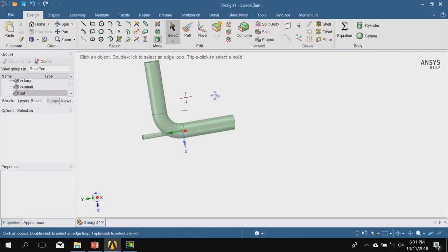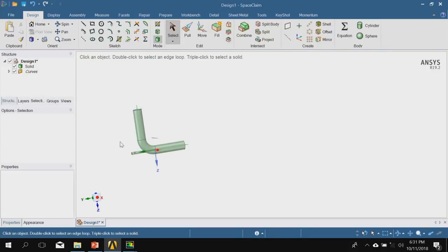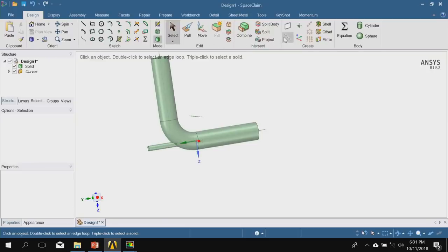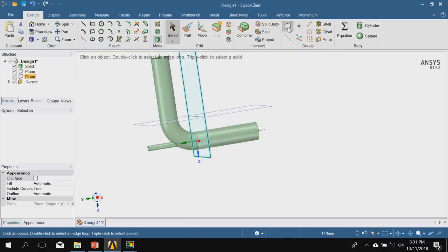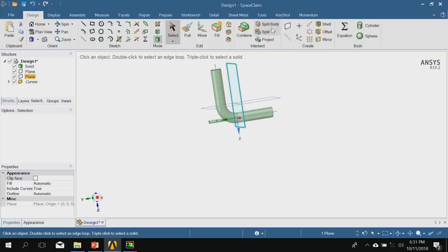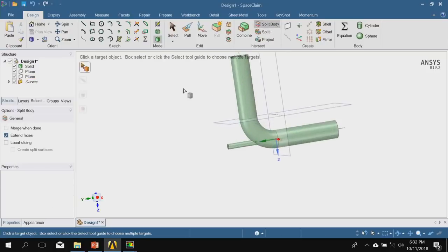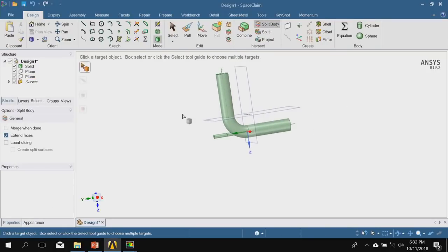For the purpose of generality, there is one additional step that you need to make if you have multiple objects. Imagine if these objects were split together in your CAD model. And in fact, we can kind of reproduce that situation by splitting them here by using the plane. If I select this edge loop over here, and I insert the plane, and another edge loop over here, and insert the plane as well, I can use the split body operation and then split these into three different sections.